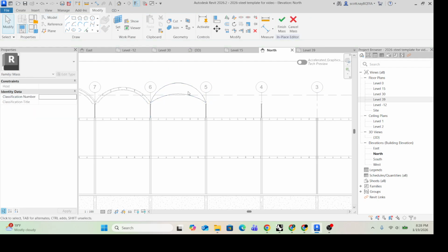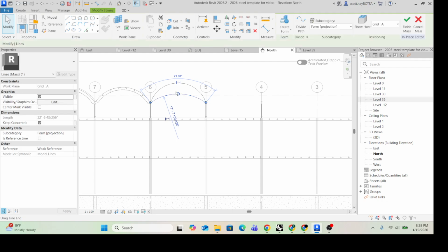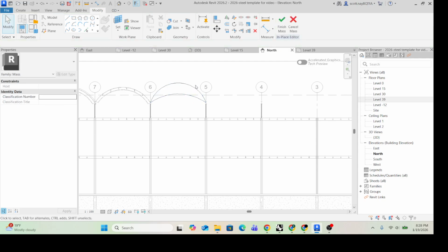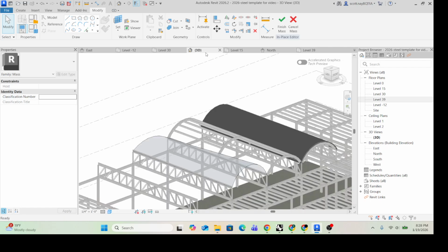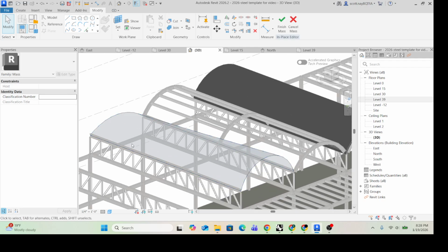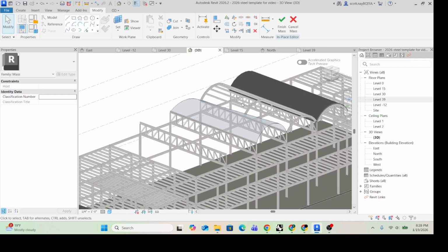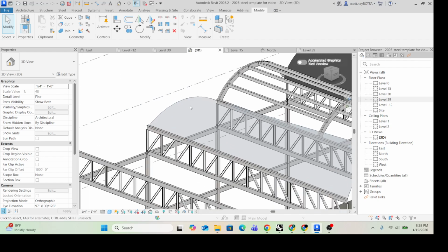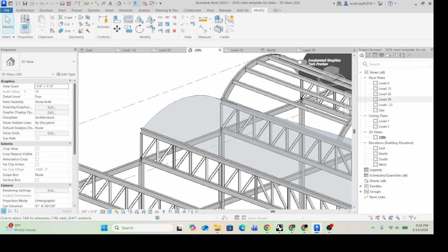So I've got two different sizes. I need to highlight them both, and then I can create a solid form. And now, since they're at different heights, Revit doesn't try and make some giant circle. It understands the path we're trying to follow. So I can say finish mass. You can close out this warning message. And now we'll see if this lets us work with this particular version.